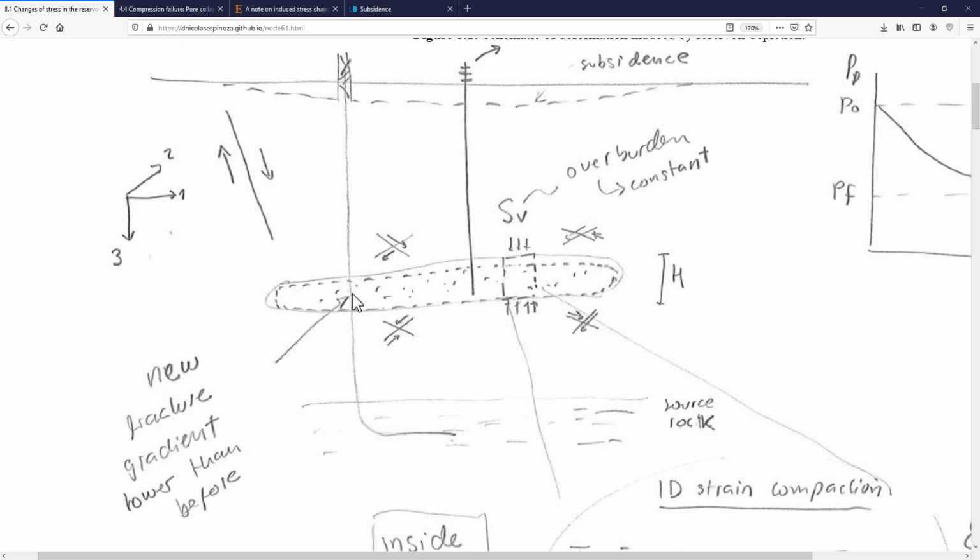And that decrease of total horizontal stress, if we are in a normal faulting or in a strike slip regime area, is going to cause a decrease of the fracture gradient, so that when I drill to that formation, I might encounter problems of lost circulation, because as soon as I hit this formation, the weight of the mud might be enough to overcome the least principal stress, which in this case is going to be horizontal, and cause an unintentional hydraulic fracture within this formation.